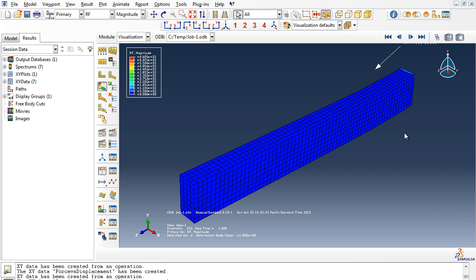You have to debate whether to model that contact interface as a layer of glue, or if you wanna completely exclude the glue from the analysis, which I think is appropriate based on what I've read. It doesn't affect the results that much. And then you have to monitor strains on the plate itself and strains on the concrete, because the plate is going to help the concrete carry more compressive strain, so the tensile strains are going to be less, and so on and so forth. So take it from here.